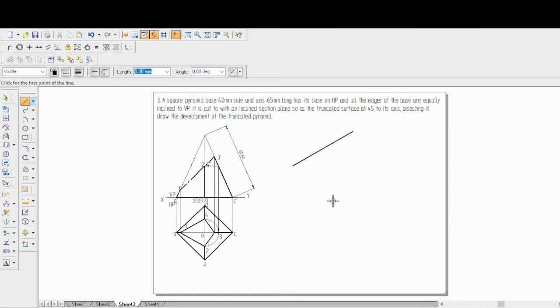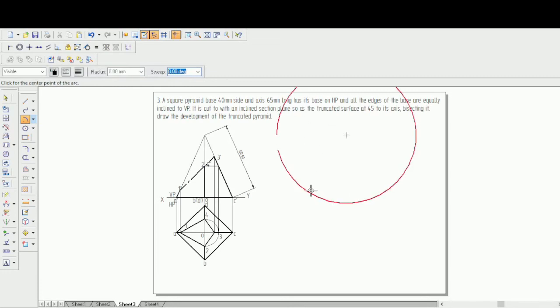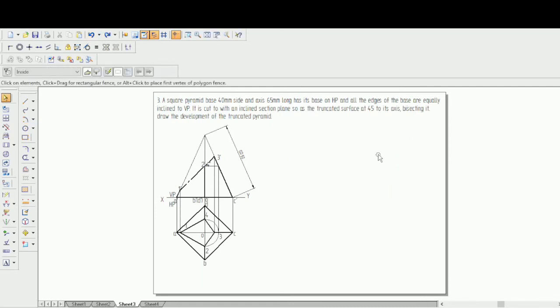Later, once you do that, instead of drawing a line, don't draw a line, you can just use that for cutting an arc. Go to arc by center point. Give the radius as 70.89. Don't draw a line but cut an arc. Keep the center somewhere. Draw it correctly. So go to arc by center point, give the radius as 70.89. 70.89 is nothing but this length.